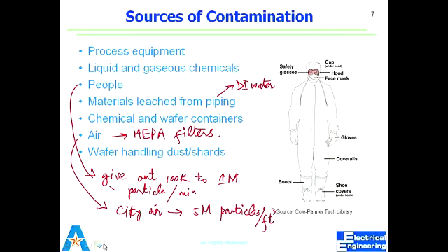What do you think, will the airflow of the hood be mixed with the common airflow of the clean room? It's not, because it has many more chemical vapors. So that's treated separately and sent out. And then of course, we have handling. These are the handling things, tweezers and all those, which can bring in chemicals. Humans give off 100,000 to 1 million particles per minute, and city air has 5 million particles per cubic foot.